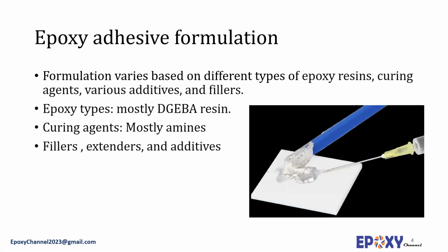To achieve an adhesive with the desired application characteristics, formulating is necessary, and therefore, currently numerous epoxy adhesive formulations are available. However, the majority of current commercially available epoxy adhesives have been formulated based on a surprisingly small number of ingredients. In case of the resin binder, various epoxy systems can be employed. They can range from very simple primary aliphatic resins with low molecular weight to more complex resins with higher functionalities or hybrid systems, for example, nylon epoxies, polysulfide epoxies, and epoxy phenolics.